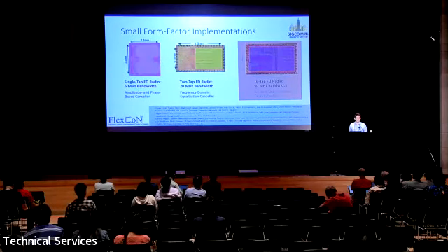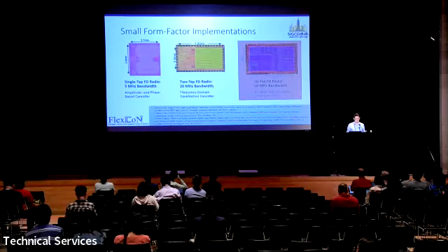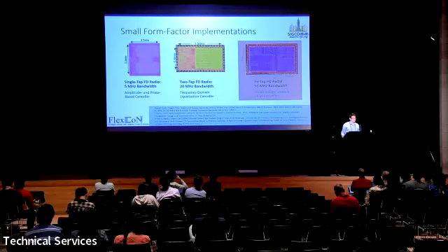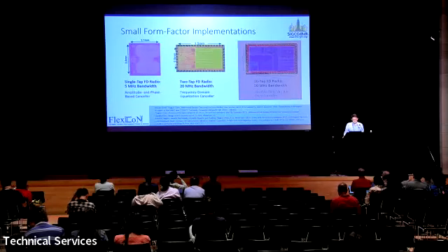So here at FlexCon, we've developed 3 generations of these small form factor IC-based cancelers. Now, generally, you find self-interference cancelers to be delay line based, which makes them very bulky. We've worked on switched capacitor technology to bring down that size to 2 millimeters by 4 millimeters, right? And the third canceler that we're demonstrating here today is the most advanced canceler we've worked with to date, featuring a 16-tap full duplex radio, which can perform cancellation across a 50 megahertz bandwidth.